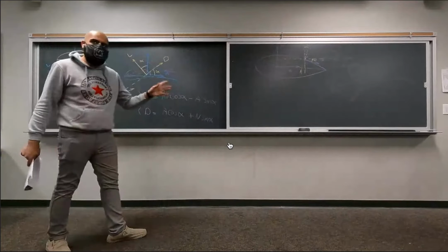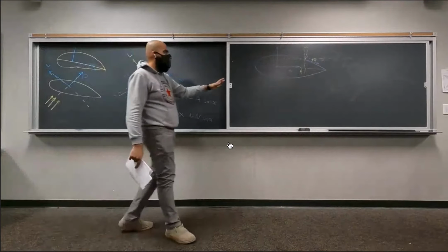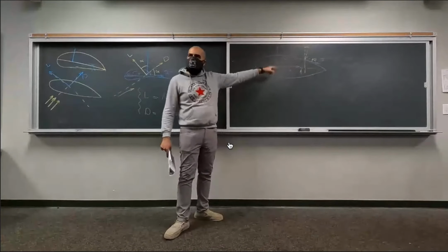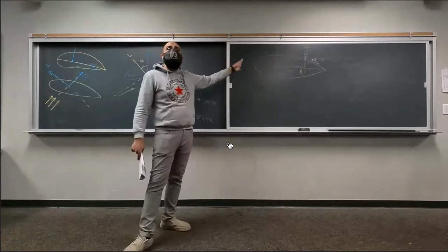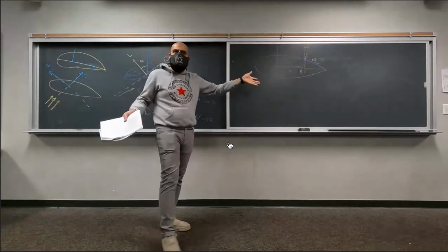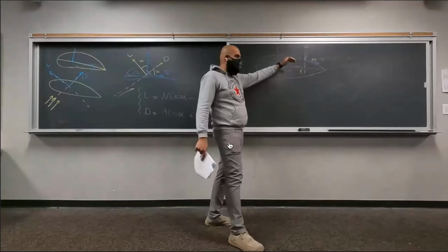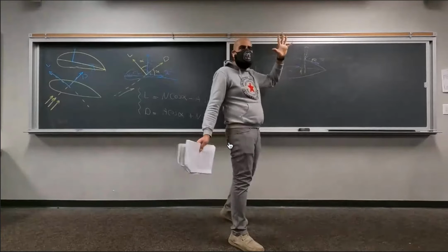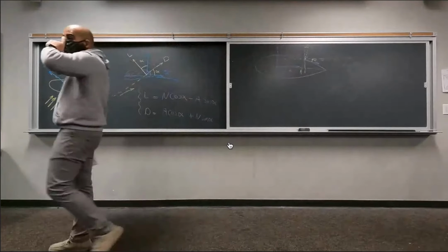And this theta here depends on your curvature, the curvature of this airfoil. So this theta is a design parameter, right? This is not something you have to find. This should be given to you by the person who has designed the airfoil, right? As long as you have the curvature of this airfoil, or whatever the wing, the object, you should be able to find that theta. You should be able to integrate over that theta. Does this make sense?